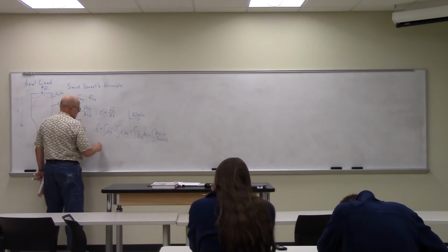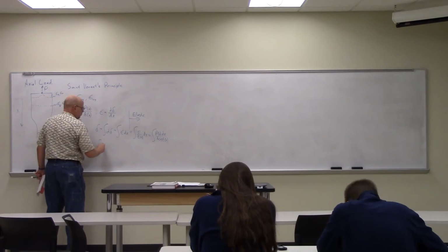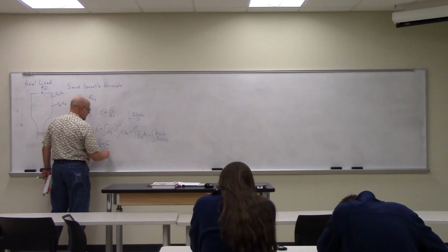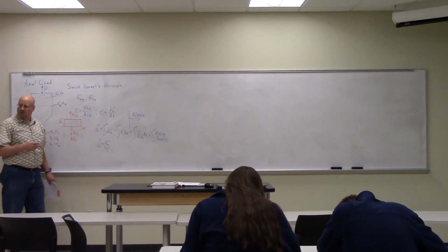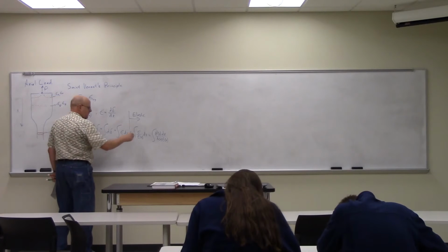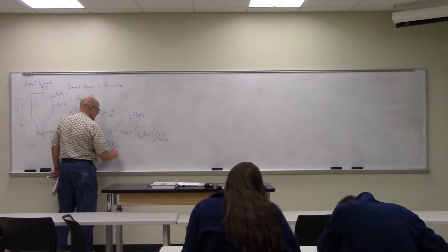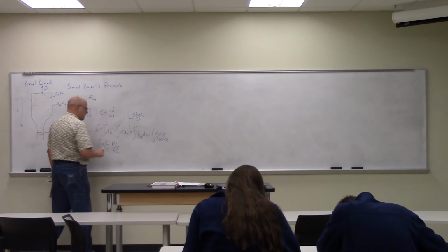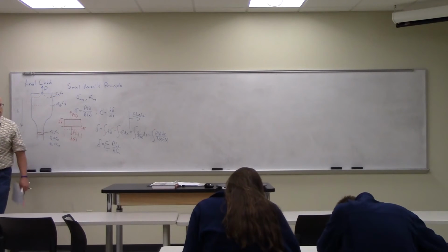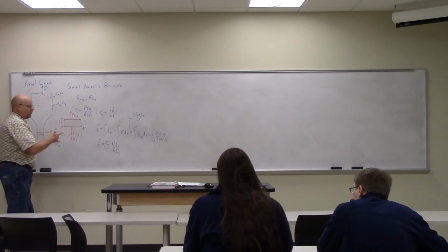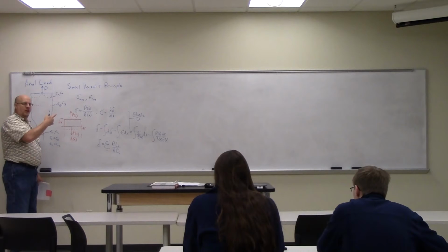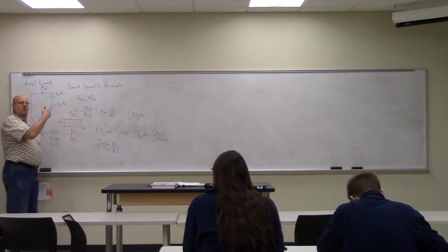So what I'm going to end up with then, in most real cases, is that delta is going to be the sum over a number I of sections of the integral of that, which is P sub i, L sub i, over A sub i, E sub i. Where it's uniform for each section, and then there is a step change to some other condition for the next section.